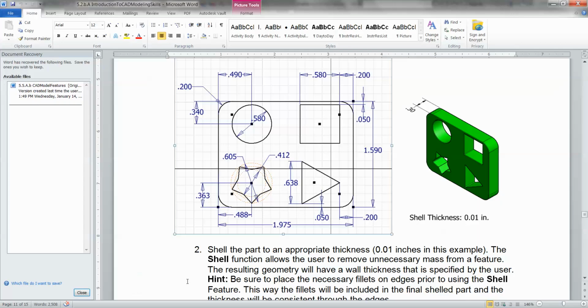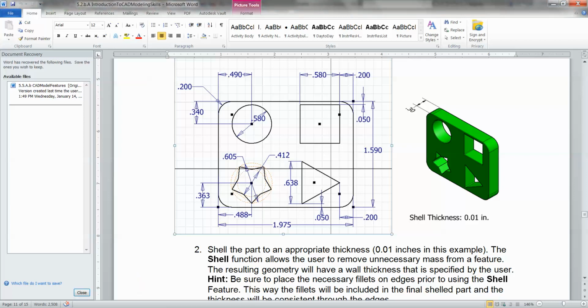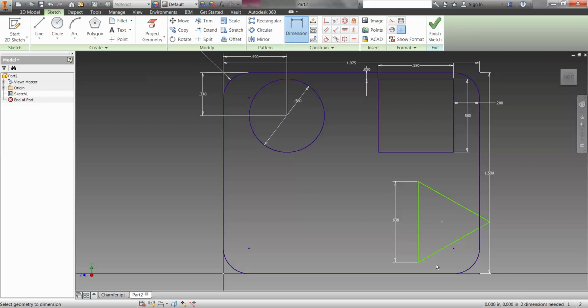Now we just have to get it into the right place, which is 0.050 inches up and 0.20 inches over. So let's come and do that. And so the dimension to the bottom and the bottom corner, this is 0.050, and then we have that 0.2 inches over. Now we're in that shape again where if we dimension it, it's going to stick out further, so we need to get it inside our shape.